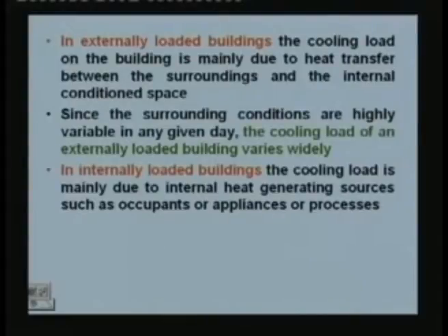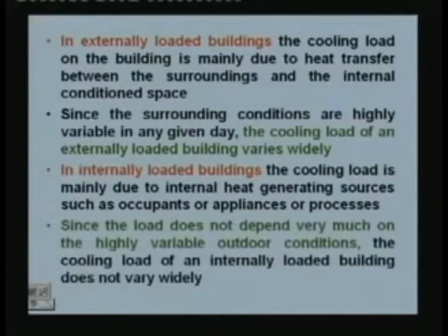In internally loaded buildings, the cooling load is mainly due to internal heat generating sources such as occupants or appliances or processes. Since the load does not depend very much on the highly variable outdoor conditions, the cooling load of an internally loaded building does not vary widely. For example, consider a theater. A theater can be treated as an internally loaded building because the heat generation due to the occupancy inside the building generally is much higher than the external loads.